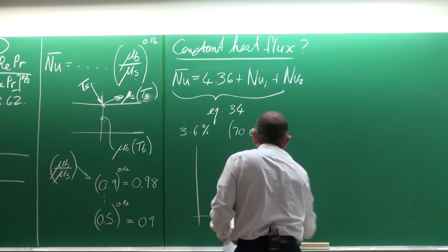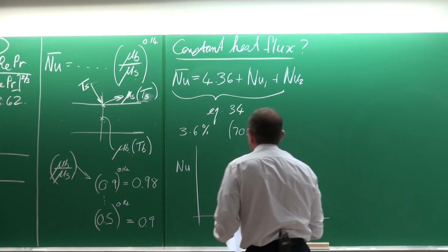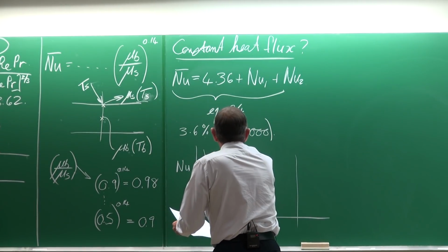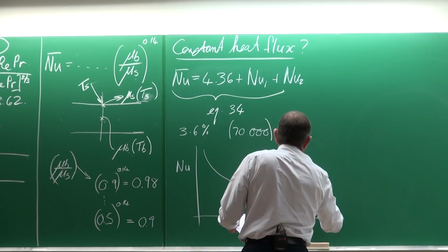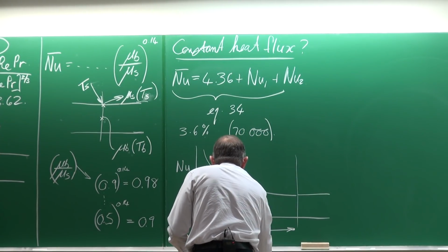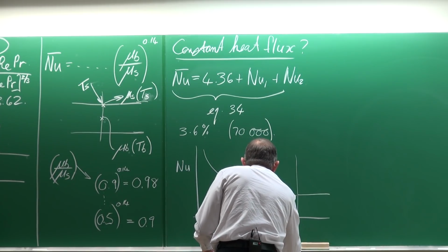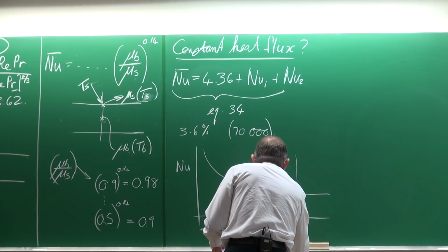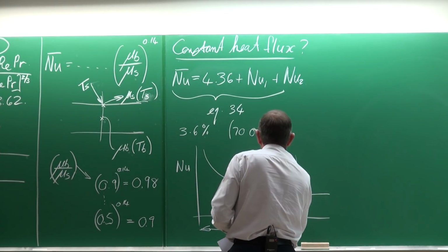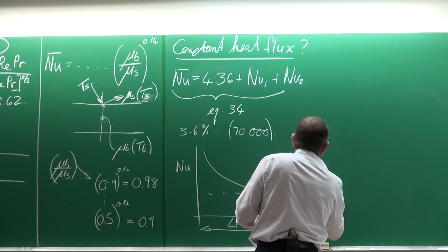So that equation, and you will understand later on when I start doing the mixed convection part why we're doing that. So it shows that, firstly, this distance, LT, is equal to 0.12 Reynolds Prandtl diameter, and that value would then go to 4.36.